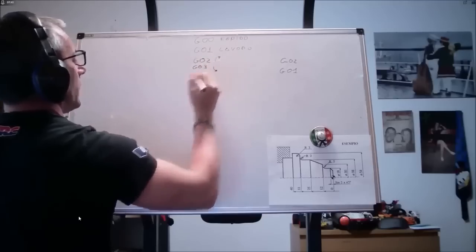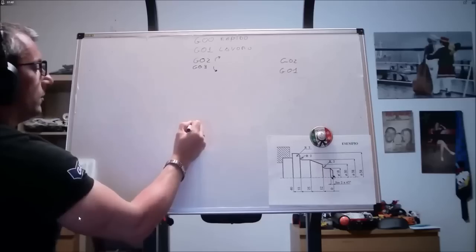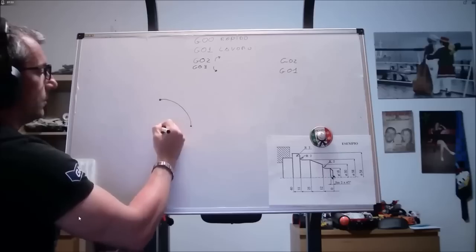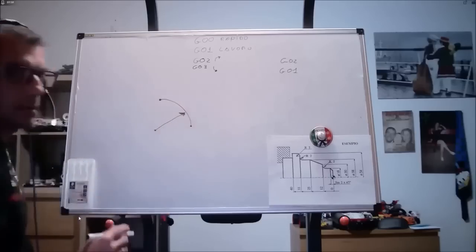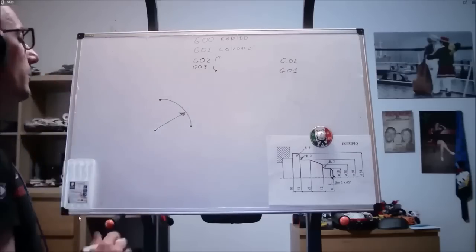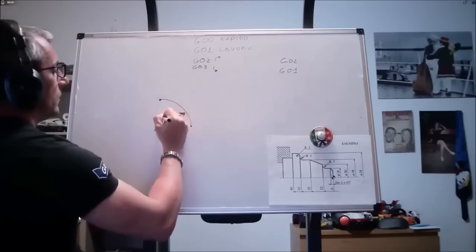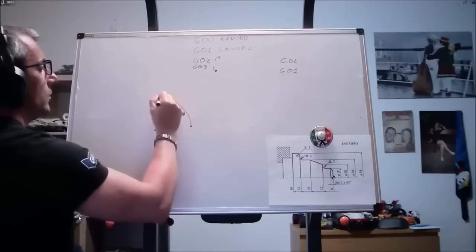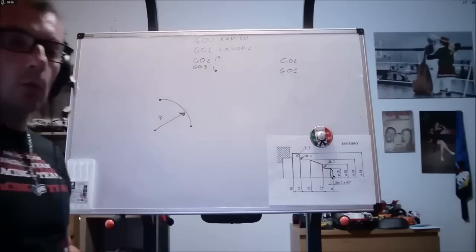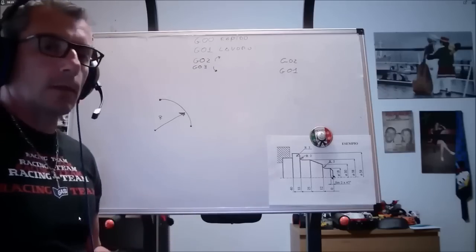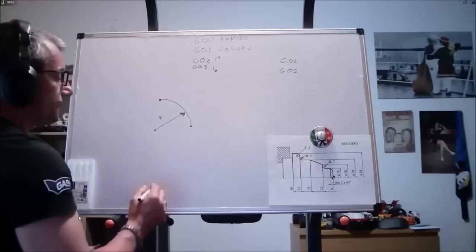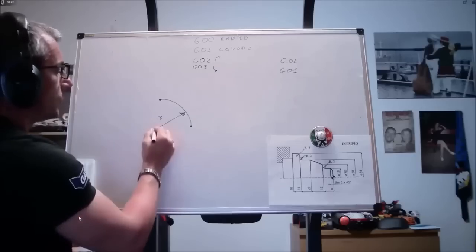What are these things? They are the starting point, the ending point, and either the center or the radius. Putting in 4 would already be a problem. So, ultimately, we are quite lucky because CNC programmers have understood that when I provide a starting point and an ending point, I only need to give a radius, and there will be one and only one circle, in this case passing through these 2 points. Then the center point was required.